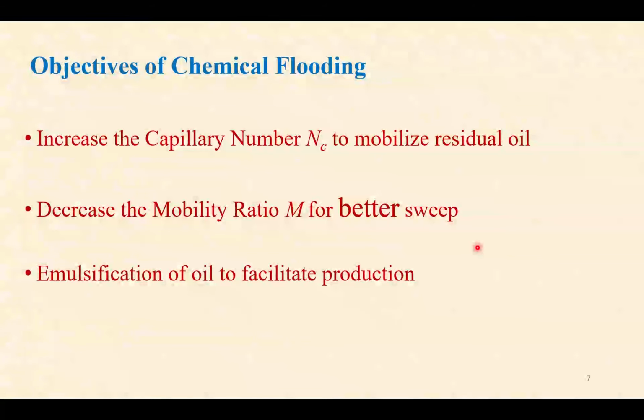So what are the basic objectives of this chemical flooding? The basic objectives are, you have to increase the capillary number to mobilize the residual oil. This capillary number, you know, is basically the ratio of the viscous force to the interfacial force.